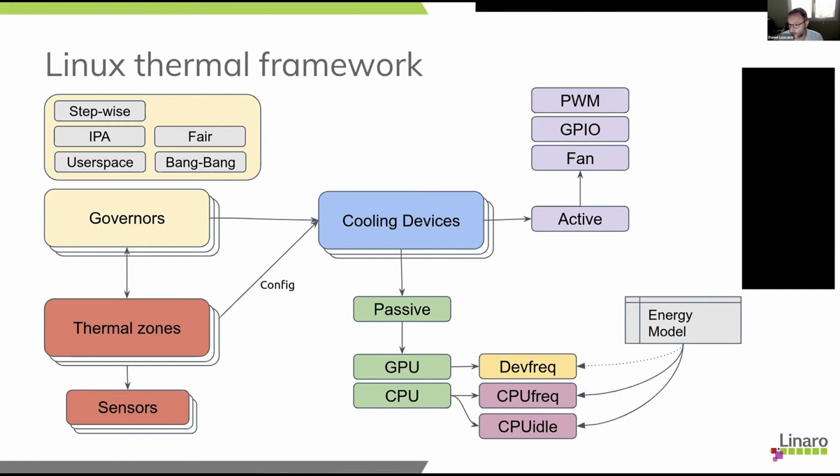So we reduce the OPP when we have too high an OPP. And then we have a specific case for a CPU: if cpufreq cannot work, or if the CPU is not DVFS capable, then we can mitigate with idle injection by forcing the CPU to do nothing during some amount of time. That allows the CPU to cool down during this moment.